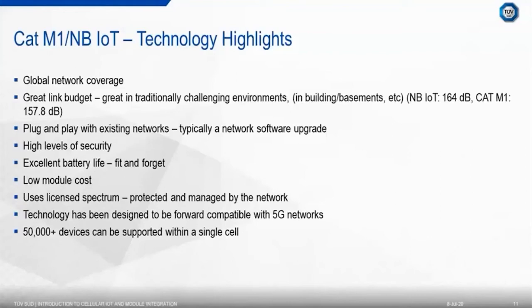It has the benefit of being plug and play with existing networks. On the operator side, it's usually a software update to existing infrastructure, and using the existing networks, security is inherited from the network in terms of data transmitted to and from the device. Battery life is greatly improved due to infrequent transmissions, numerous power-saving features, including deep sleep modes, and switching off of circuitry during operation times to realize useful device battery life of up to 10 years. Due to the reduced complexity of the modules versus a standard 2G, 3G, or 4G module, their price is much lower and down to around a few dollars.